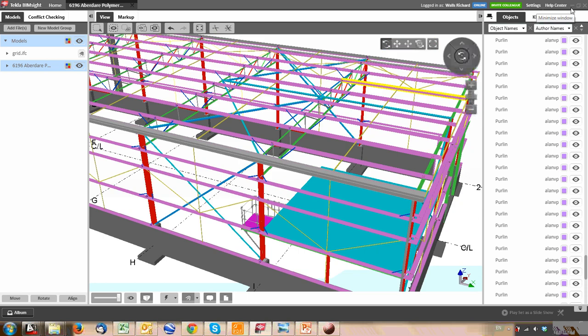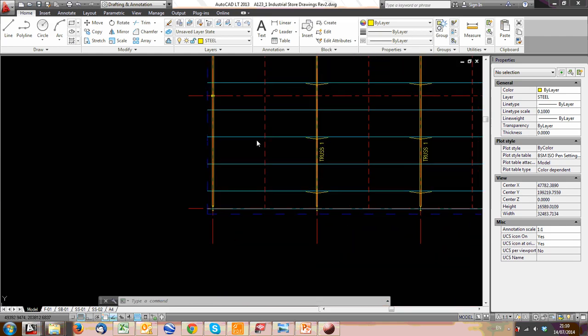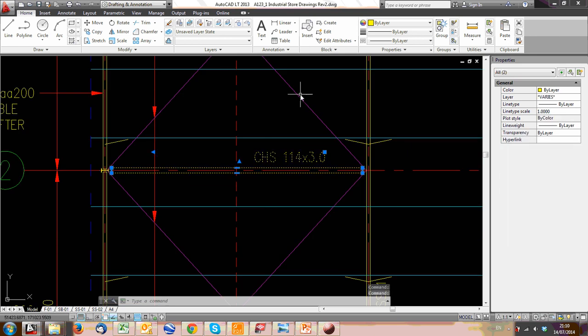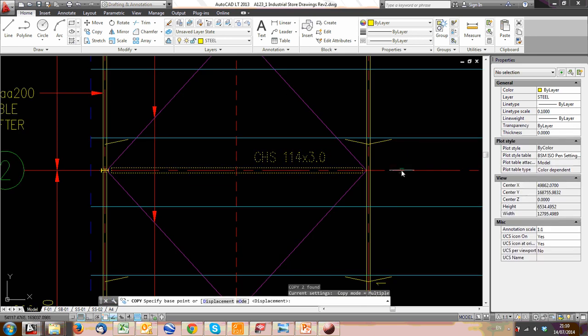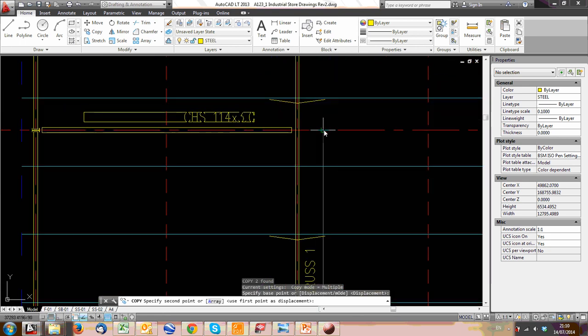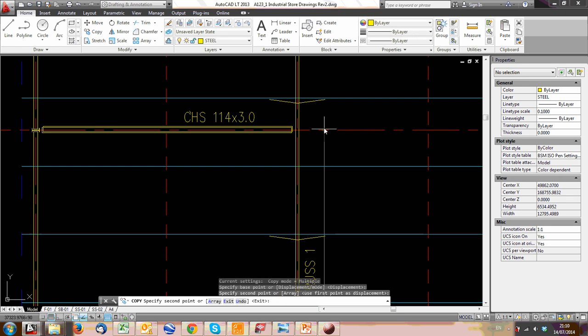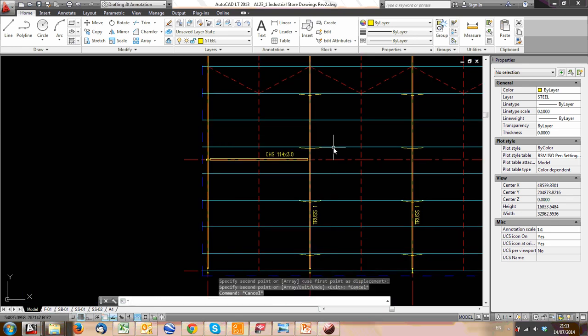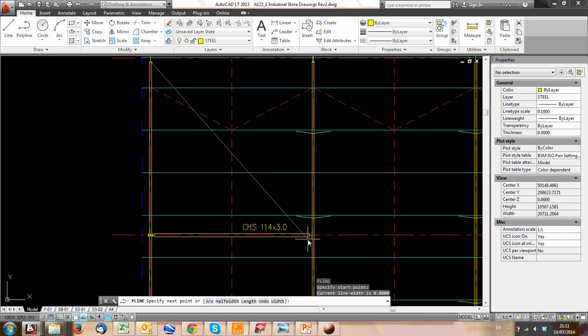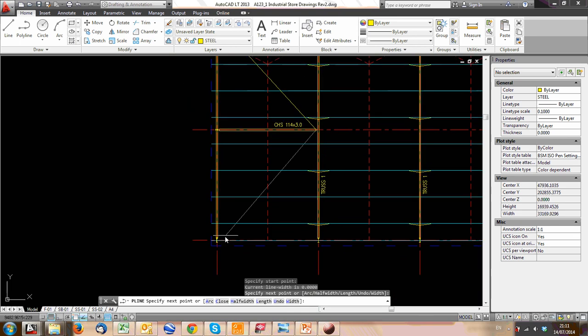Right, so let's draw those. So we can just put it on a slightly thicker line. But for now, I'm just going to be lazy and copy that over. If you've drawn one out, there we go. You put it in place there. There we go. And then if I'm going to add, say, a polyline with PL enter, polyline, and then I'm going to draw that from there to there to there.